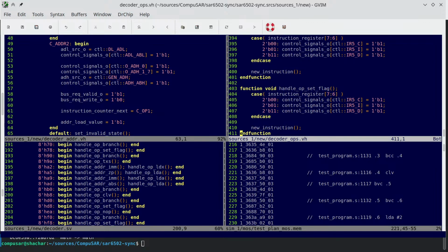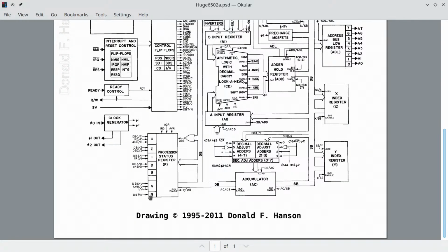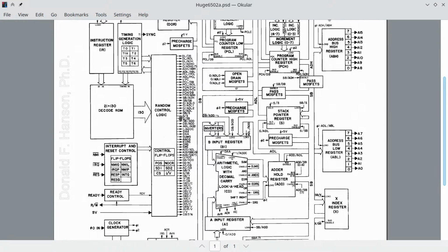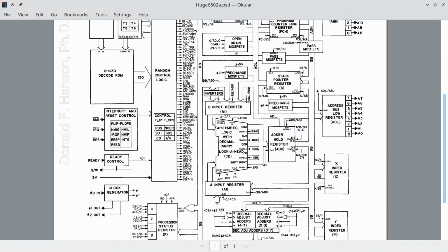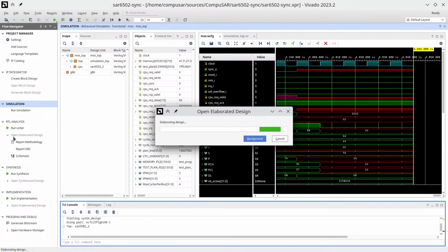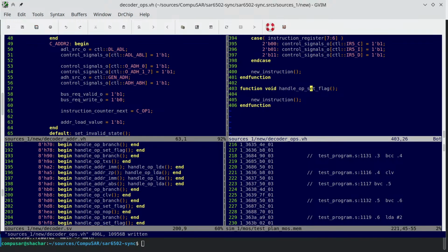And now we have a bit of a problem, because in order to clear the overflow, the control signals we got for the overflow are: take it from the data bus bit 6, take it from the ALU overflow, or set it to 1. We don't have set it to 0. Also, you'll notice that the data bus doesn't have any bit generation. However, while here the special bus doesn't have any bit generation, in our implementation it actually does have them. It could help to not duplicate.